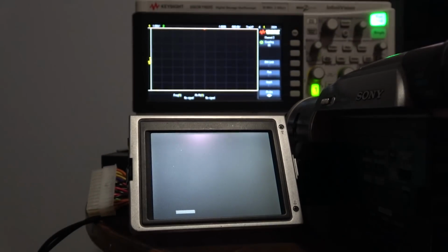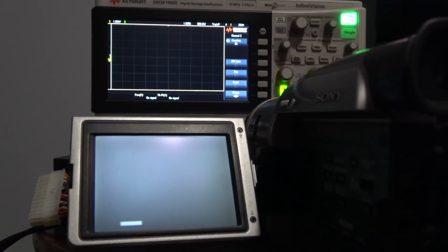But that's why I wanted to use a resistor value that was twice that of the potentiometer. That way, no matter what position the potentiometer is in, it will still go above the halfway point of the voltage when the button's pushed. Otherwise, the position of the potentiometer might affect it too much to get a good reading. So let's take 256 divided by 3, which is 85. So we'll basically say, for anything above like 128, we'll consider the button to be pushed.